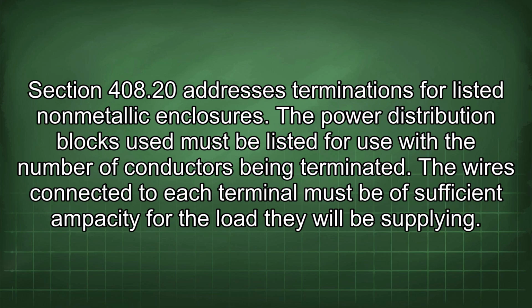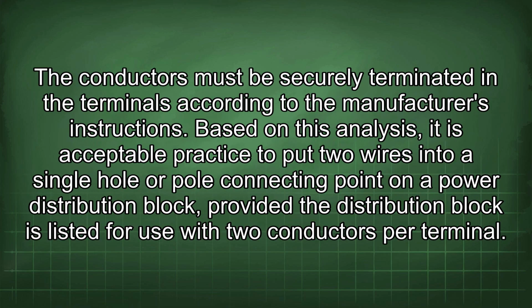The power distribution blocks used must be listed for use with the number of conductors being terminated. The wires connected to each terminal must be of sufficient ampacity for the load they will be supplying. The conductors must be securely terminated in the terminals according to the manufacturer's instructions.